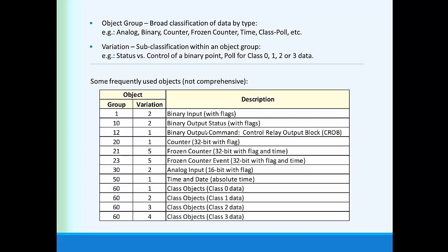That might be of interest, but there is also recognition that doing that frequently enough to keep the master station updated in real time, 24 hours a day, 7 days a week, when you've got thousands of feeders throughout a distribution area, is a tremendous burden on bandwidth. So to use the bandwidth more efficiently, DNP defines a type of poll called an event poll. And what the event poll does is it basically says, look, don't tell me what the data is right now. Tell me when something interesting happens.